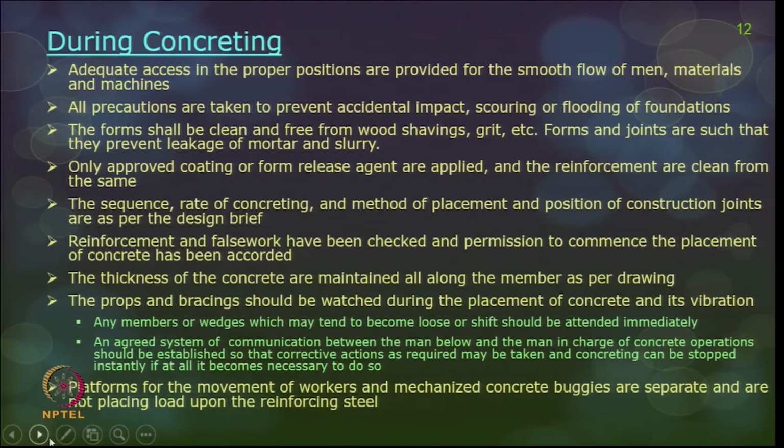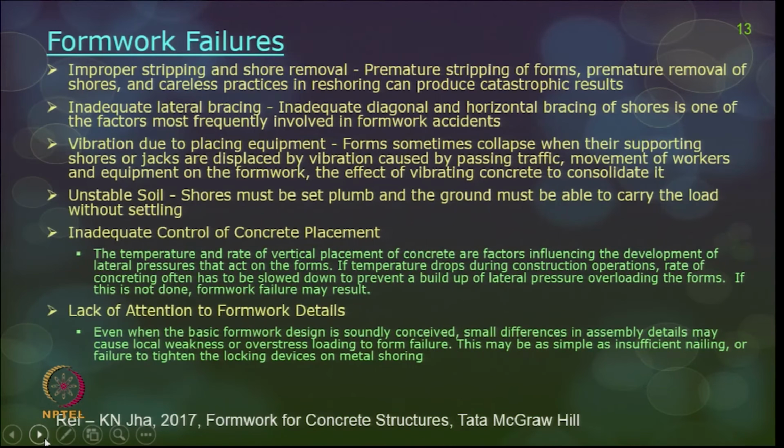The props and bracings should be maintained for proper strength, especially during the placement of concrete and vibration. The concreting may also have to be stopped when catastrophic issues are happening in the site. Platforms for the movement of workers and for the mechanized concrete buggies should be separate, and the load should not be placed onto the reinforcement, and it should not go to the reinforced steel.